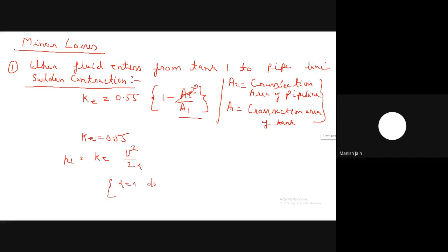due to turbulent flow. For laminar flow, alpha is 0.5. For turbulent flow, alpha is 1. Just substitute the value of K, 0.55, multiplied by V square. V value is 0.6083. So 0.6083 square divided by 2. When you solve, the value will come 0.102 joules per kg.